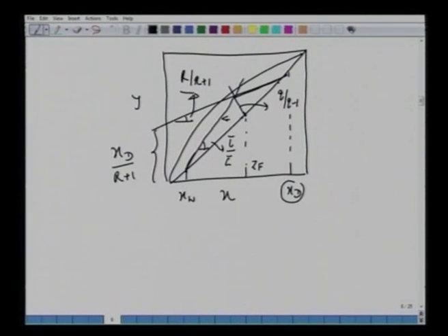So this is all expected because we have three equations. The third is the intersection of the operating line for the stripping section and the enriching section. So fix any two, you get the third. You fix these two, you get the third. You fix these two and connect with this ZF, you will get this Q over Q minus 1.